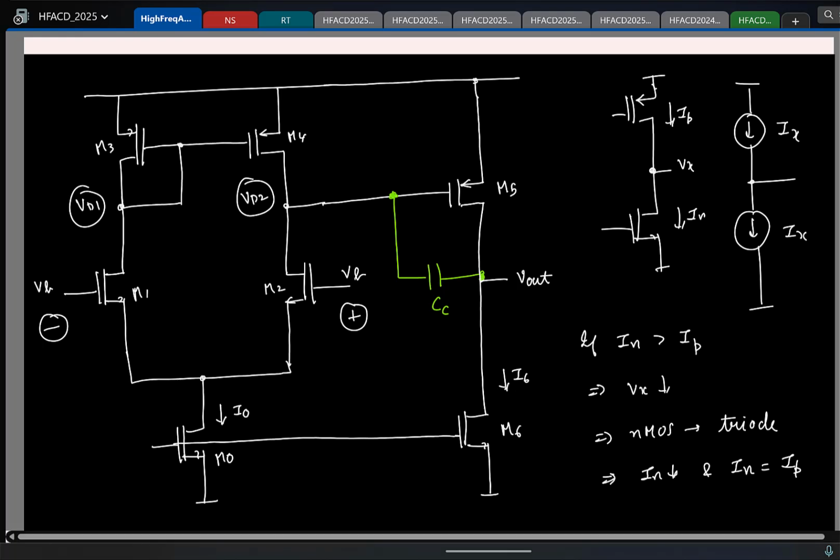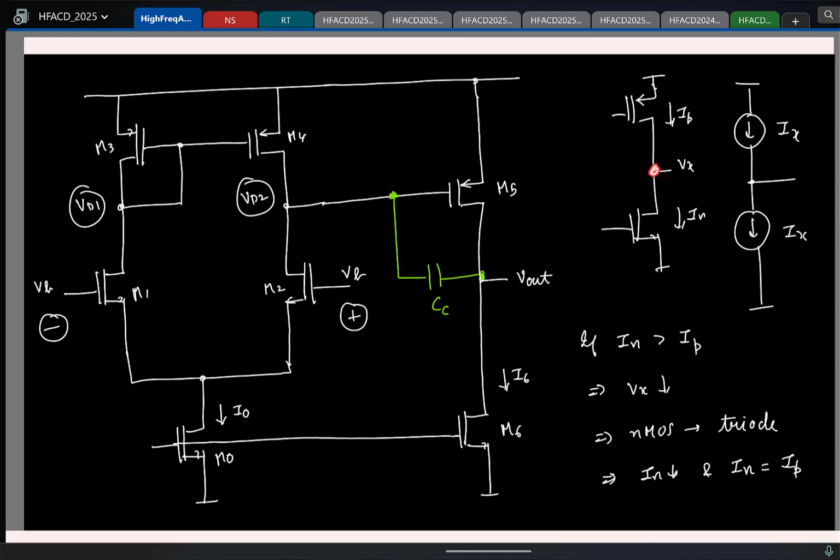No, I mean, yeah, that's the simplest thing, right? I mean, output is defined. The drain voltage will reduce and reach a value so that the NMOS will be in triode and the current equals the PMOS current. But that is not something you want, because one of the transistors is going to triode. Opposite will happen if PMOS current was greater than the NMOS current.